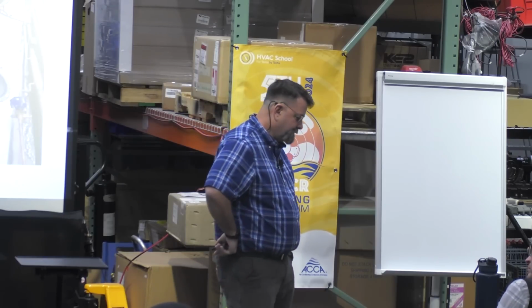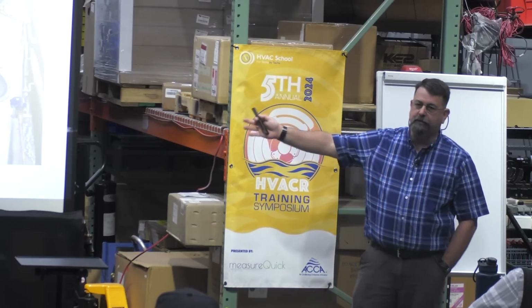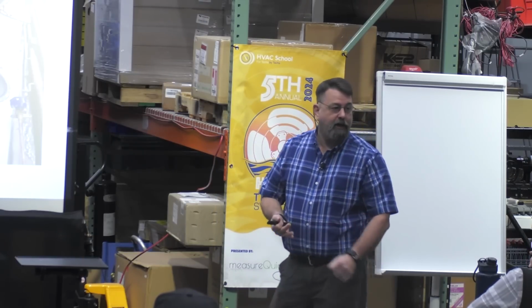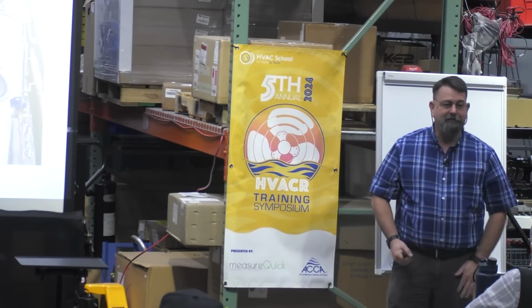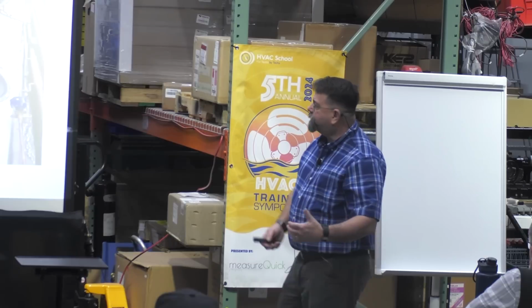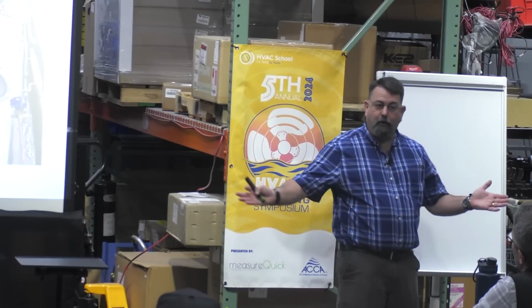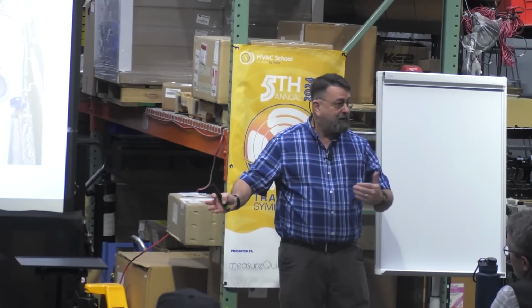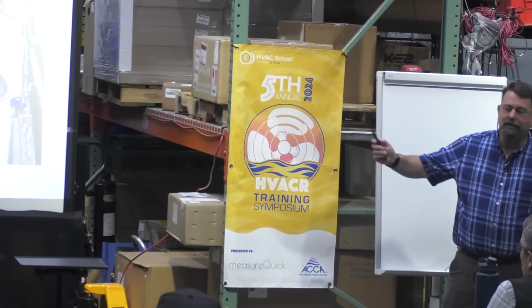Now, if you have something like a vent that's going through that air curtain, then that can actually disrupt the air curtain and actually create problems. Yeah, absolutely. There's a whole troubleshooting process, just like everything else, right? There's a process that if I've got airflow problems, these are the things I'm going to check. Shelves that are too long, the store has violated my load limit, things like that. In the residential world, somebody leaving the front door open and the back door open at the same time tends to cause a temperature problem, right? Because the air is blowing right through the store. Yeah, we got the same thing going on. We got exactly the same thing going on.